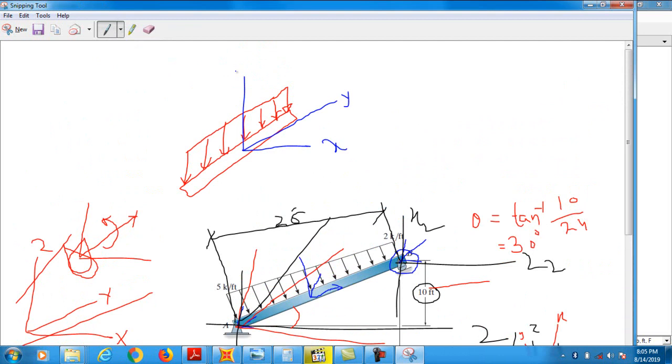If I don't change, let's say I select the gravity direction and I assign the load to this line element, the load will be somewhat in this pattern, and I don't need to assign the load in this pattern, because the load is not perpendicular to the element. I need to assign the load perpendicular to the line element.